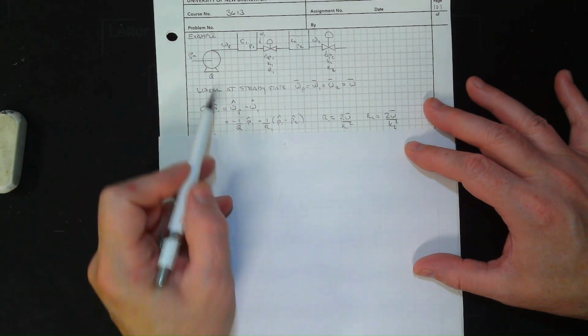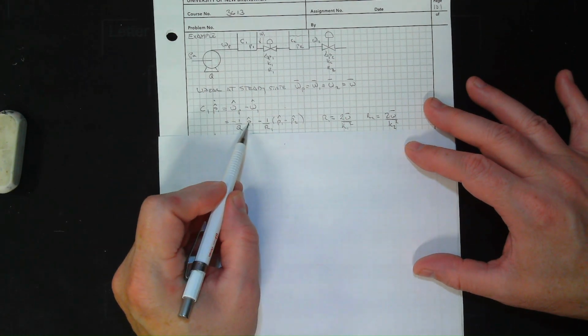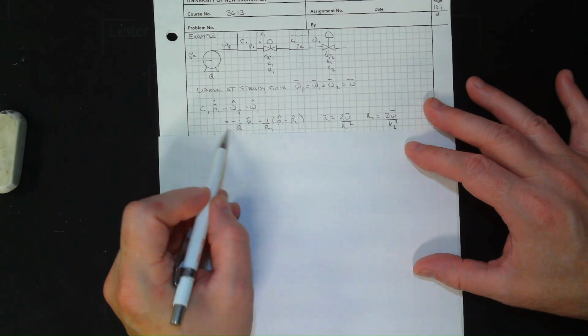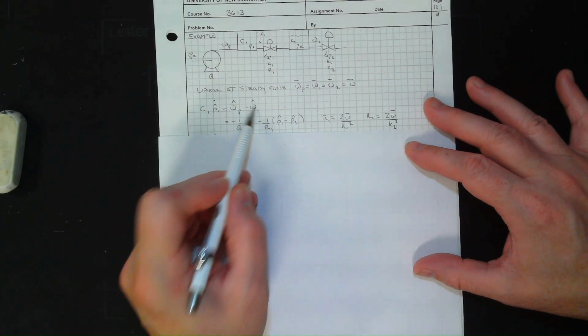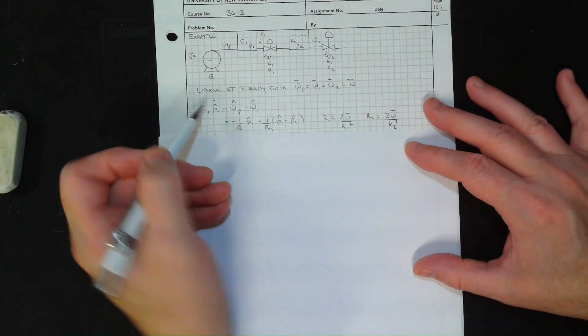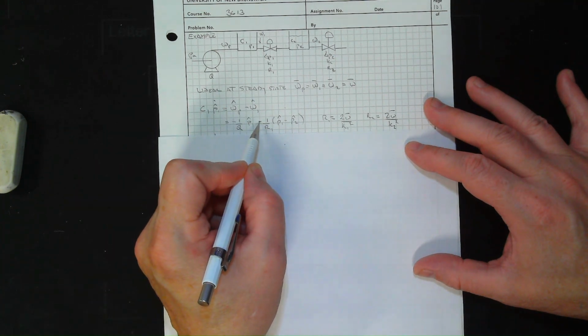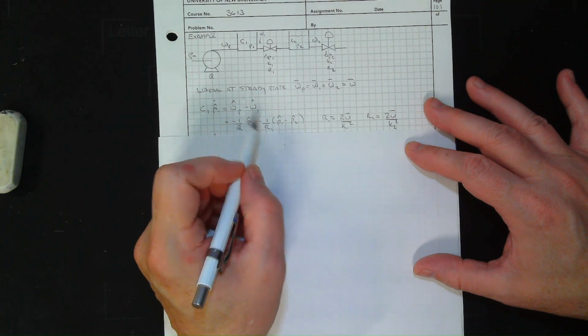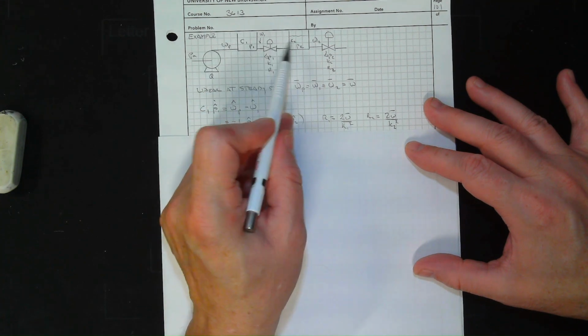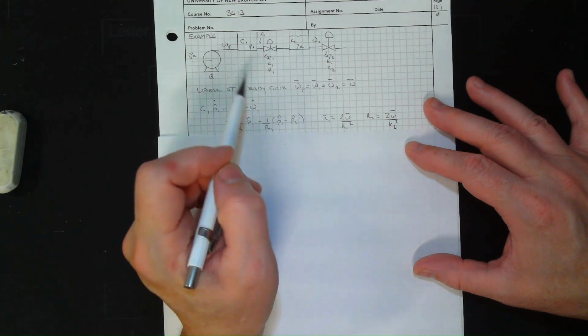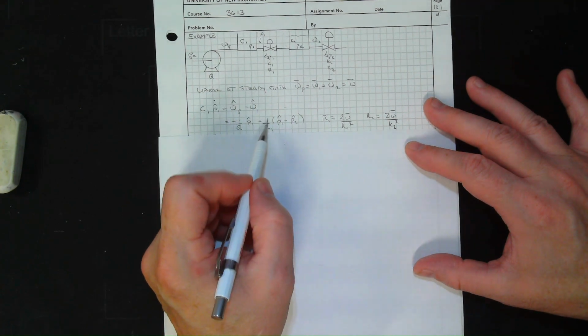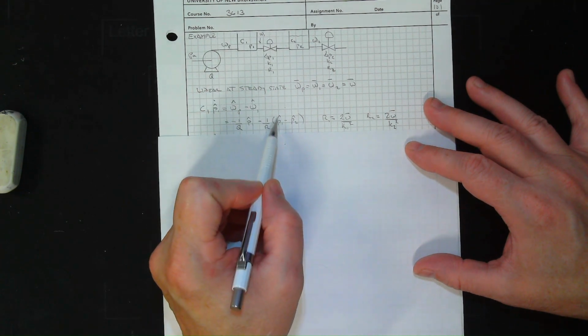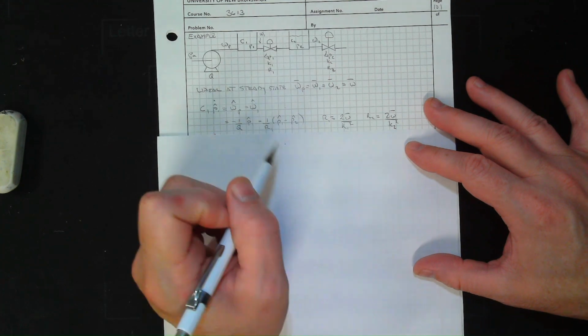And then here we have our Q, it's minus 1 over Q. This is the input. Then we subtract off omega 1. So that's where that minus sign comes from. But then this will become 1 over R, P1 minus P2. We'll be dropping in pressure. That's what will create that flow. Okay, and so we're going from P1 hat to P2 hat.